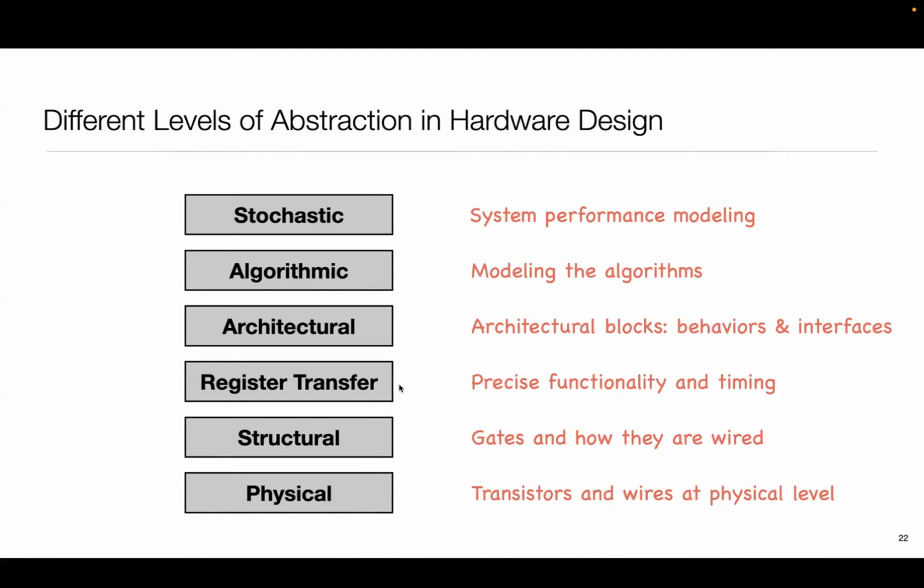So this is called register transfer level, and we'll spend time here also. Then comes architectural level. Here we start thinking about bigger blocks, right? I mean, this is a FFT unit, or this is a multiplier unit, right? I mean, we're thinking in terms of the big functionalities. Architectural blocks, what their behaviors are, how they are interconnected.